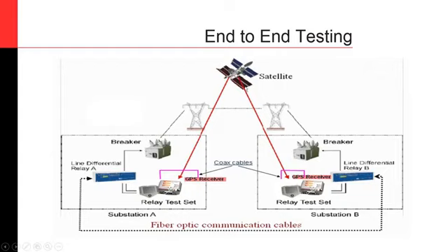If you can have a timing signal that is good for both test sets, and at the same time it's the same timing signal that is being used to guarantee the time signal of the relay, that's even better, because then you can actually see the events in both relays that happen when you're doing your testing, and you have a way of matching the operation of both relays using the timestamps of those event files.